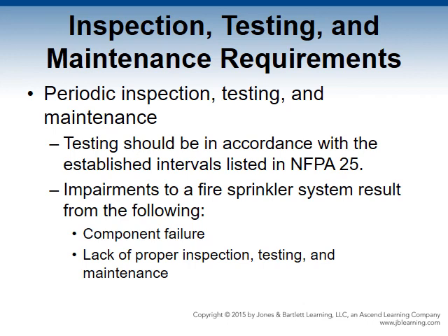Every 3 years, a dry pipe system requires a full test. Every 5 years, a sample of extra high temperature sprinkler heads needs to be tested. A sample of fast or quick response sprinkler heads requires testing initially and after 20 years of service, and then every 10 years thereafter. At 50 and 75 years of service, a sample of all sprinkler heads is required to be tested.